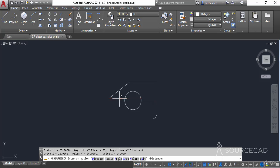Also, we have some additional values like the delta value, the delta x, y, and z. So that simply means that the coordinate value of the final point when subtracted with the coordinate of the initial point will have this result. So the x coordinate of this point minus x coordinate of this point will be 22.9363 unit. Similarly, the y coordinate of this point minus y coordinate of this point will be of this value. Now to exit this command, simply press escape key.